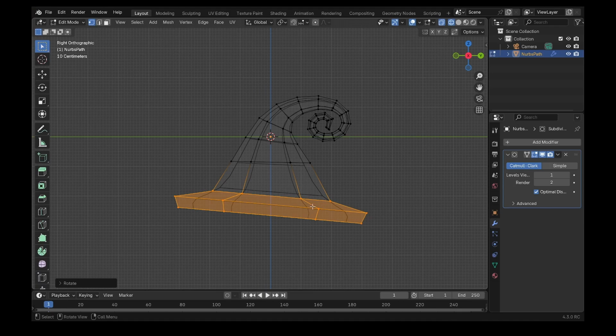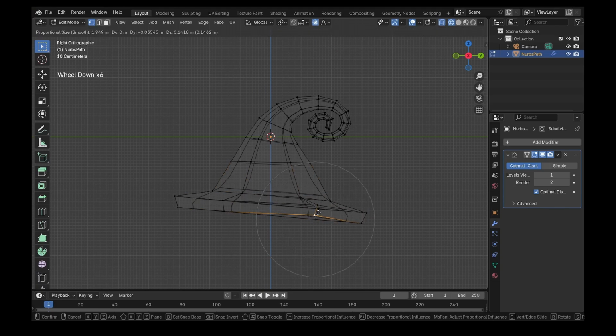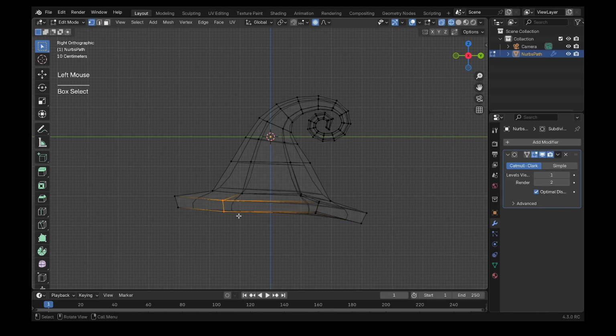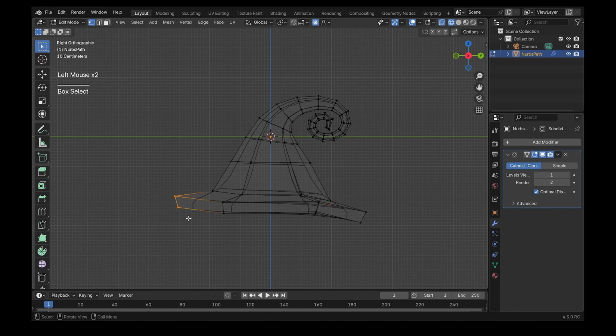While still in wireframe view, click over here to turn on Proportional tool. With this enabled, if you move any of the vertices, the adjoining geometry moves with it as well. In case yours doesn't move like mine, the size of your circle of influence might be off. Use the scroll wheel on your mouse to adjust the circle size, or use the page up and down keys.